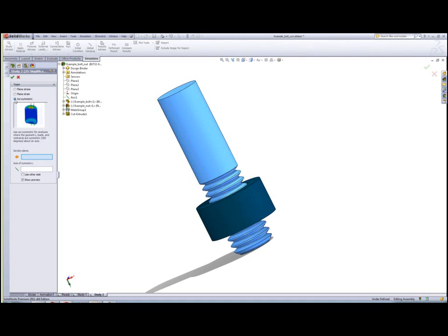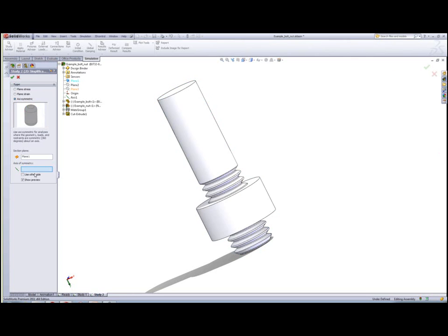This would typically be done in an early release if you take a pie cut of this and take 1/4 of it, 1/8 of this particular model, and add some advanced constraints and perform your functions in that regard. So we're going to do axis symmetric, and I'm going to choose a plane. I'm going to choose this plane there and an axis. We'll get a little preview. You can see a little yellow preview, similar to a dynamic preview in SOLIDWORKS. I'm going to click OK.